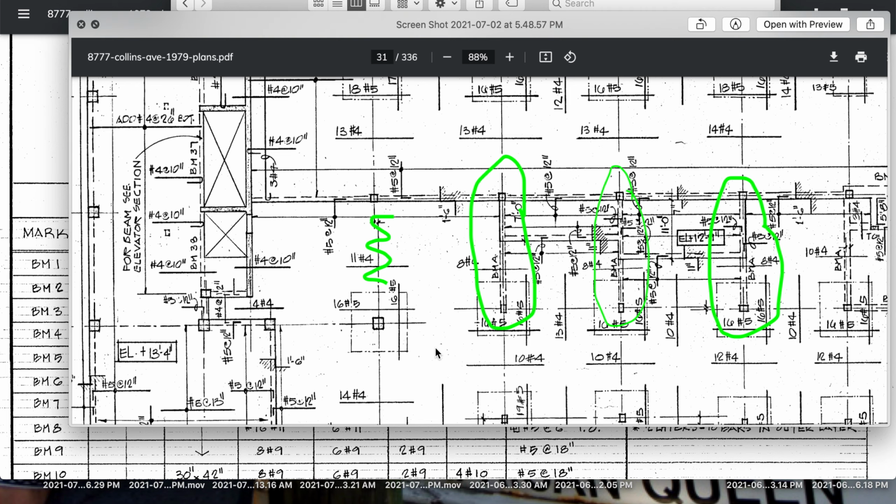I appreciate you guys trying to help me find this connection from the columns here out to the connection of the wall system here for the decking. Now, this says BMA, BMA, BMA, BMA, all the way down here, but here there's nothing. If we go to BM, BM stands for beam, but this appears to be the letter A, alpha, and it's duplicated all the way down, BMA.